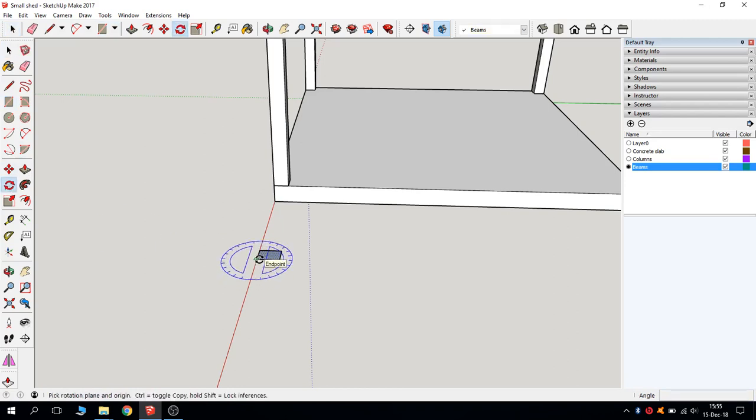Now you go here, then using arrow keys you can change that to rotate around red axis. So I pressed right, and now I have this red protractor. When this turns blue, it means it's 90 degrees. Also, if you go down, or you can just type 90. This way is also good.